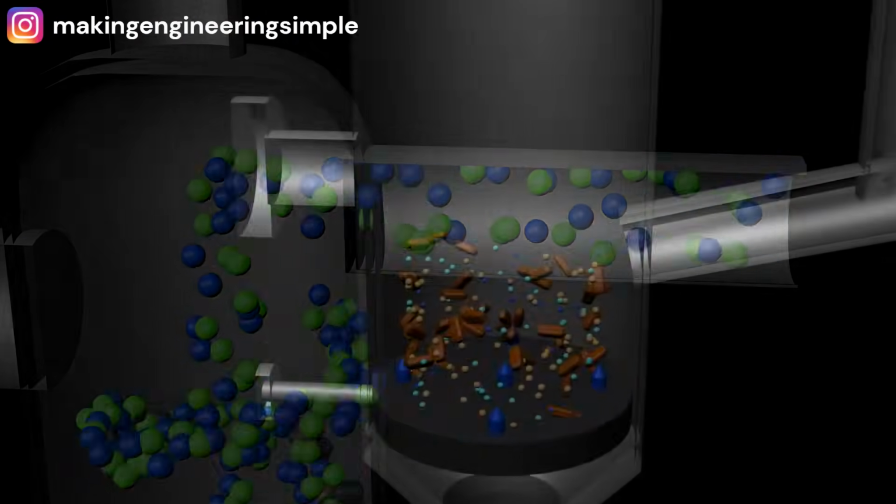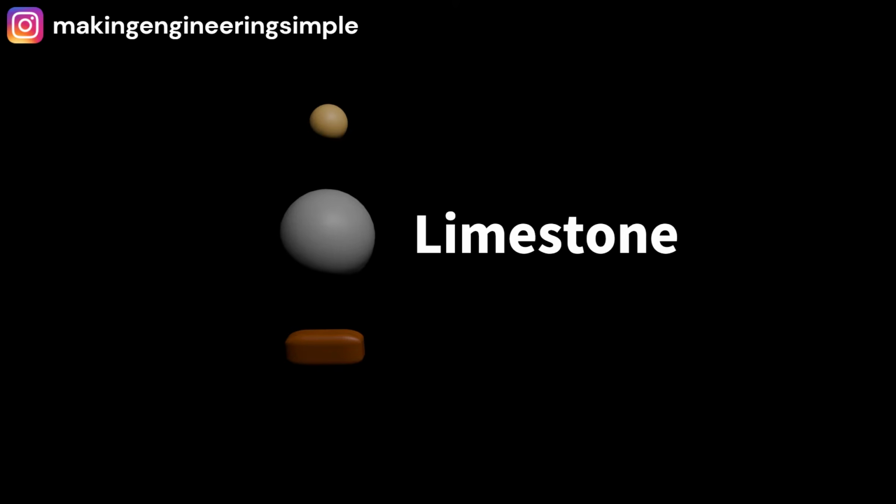The fluidized bed which forms at the bottom of the gasifier consists of bed media such as sand and limestone. The sand helps to distribute heat evenly, and the limestone helps with sulfur reduction. The feedstock is the fuel source and is commonly wood chips or pellets.